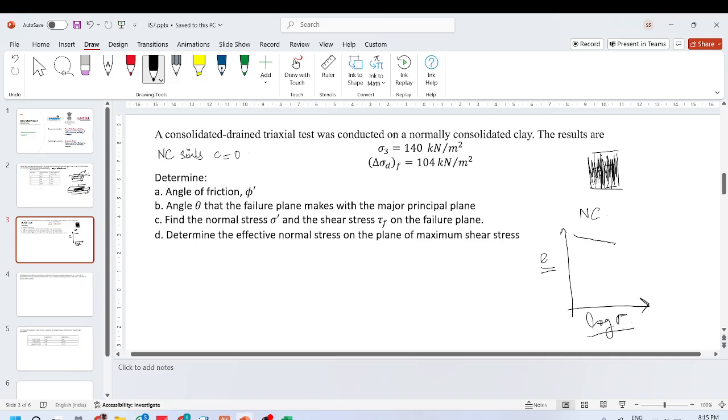But as it reaches its preconsolidation pressure, the maximum load that the soil remembers, or to be more precise, the maximum load under which plastic deformations had happened that had made the soil restructure itself, it is reached.